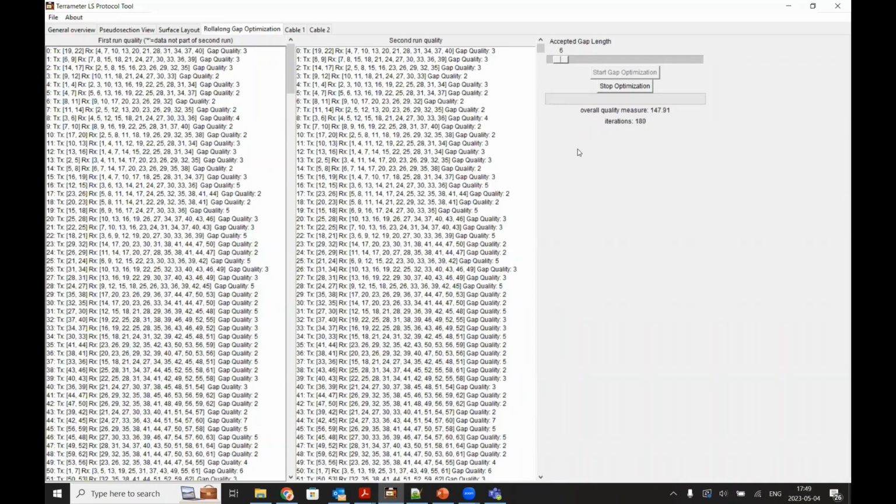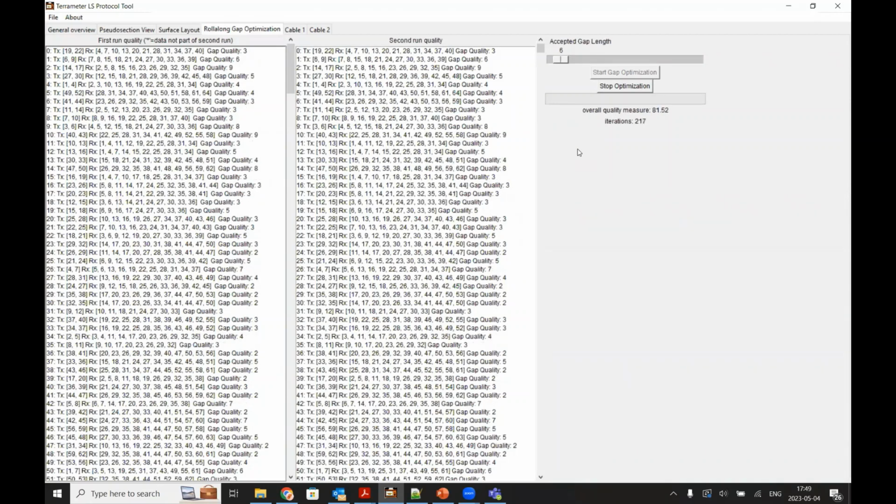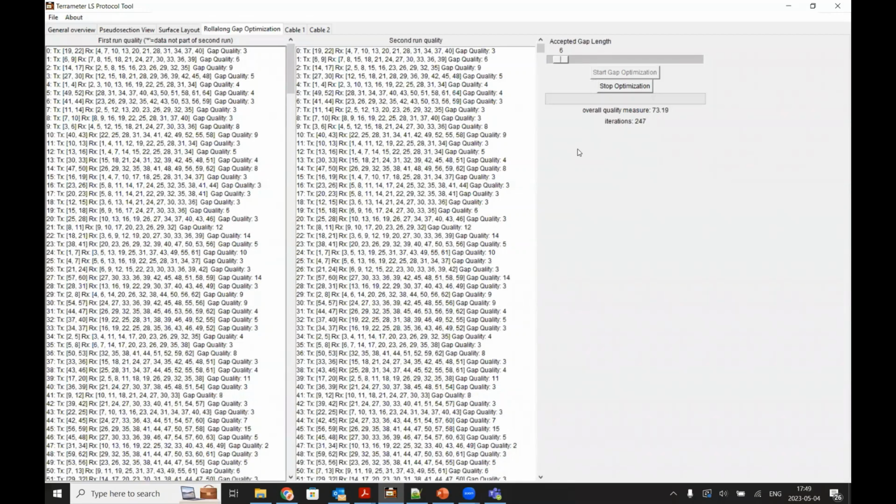And if an electrode which is still polarized is used as a potential electrode, it can have a negative influence on the data quality. So we want to schedule the sequence of measurements so that there is a resting period after an electrode has been used for a current injection, and before that electrode is then used in a different measurement cycle to measure potential.